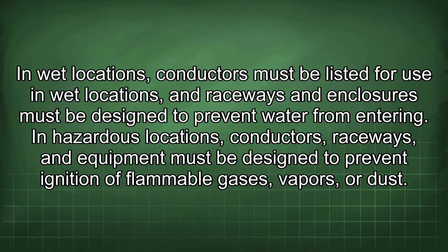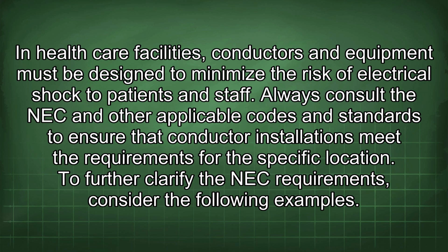In wet locations, conductors must be listed for use in wet locations, and raceways and enclosures must be designed to prevent water from entering. In hazardous locations, conductors, raceways, and equipment must be designed to prevent ignition of flammable gases, vapors, or dust. In healthcare facilities, conductors and equipment must be designed to minimize the risk of electrical shock to patients and staff. Always consult the NEC and other applicable codes and standards to ensure that conductor installations meet the requirements for the specific location.